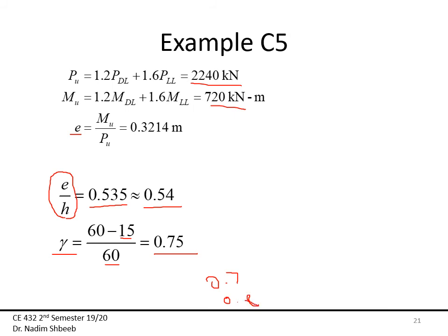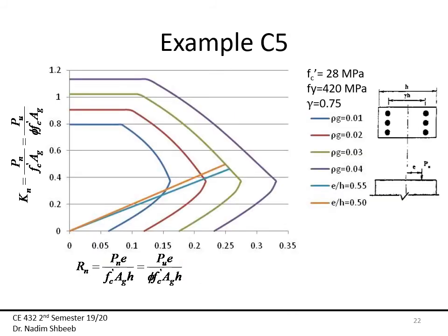What that means is that you have to do all the work that I'm going to show you right now once for 0.7, and then one more time for 0.8. So you're going to have a value for your h at 0.7 and a value for your h at 0.8. To get to 0.75, you do an interpolation between them, which is obviously going to be the value divided by 2. But I did not do that here, because I have my own spreadsheet or my own program.